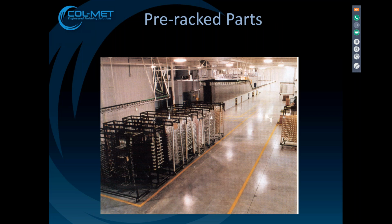That's the reason that we will pre-rack parts offline. If you're going to be processing many small parts and utilizing racks like this, in system design we need to bear in mind that they're in the footprint of the system. We need to allocate some space for not only loading and unloading the line, but pre-racking parts as well.